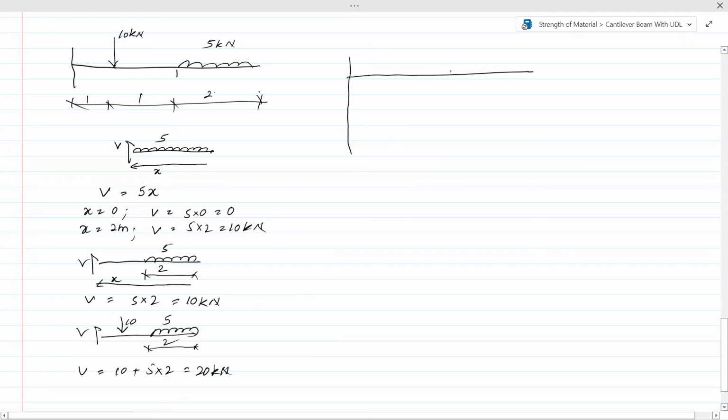First we indicate the load distribution there. We have a point load like this, point load like this. Then we draw the shear force diagram. Now here we have a linear variation. Here the shear force will be 0. Then up to a certain point we check the shear force there. The value is 10, so this will be increasing to 10. From this point onward there is no variation, as we saw previously, because it's a constant, 2 into 5.